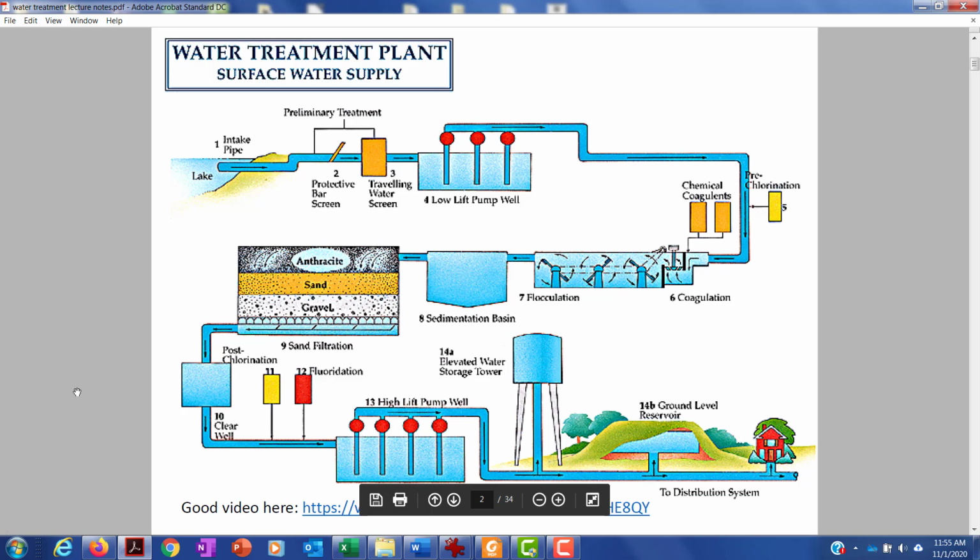And finally, I want to emphasize one other thing. Even after all this coagulation and flocculation, you can get bits of dissolved phase carbon, and when that dissolved phase carbon gets chlorinated, it creates a class of compounds called trihalomethanes, and trihalomethanes are carcinogenic. So water treatment plants are constantly dealing with this problem of chlorinating enough for the water to be disinfected, but not chlorinating so much that they produce too many trihalomethanes from chlorinating natural organic carbon in the water.